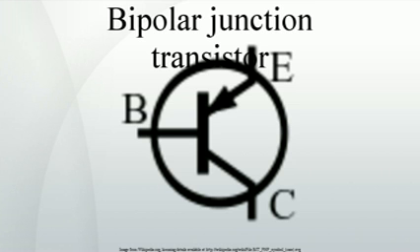PNP. The other type of BJT is the PNP, consisting of a layer of n-doped semiconductor between two layers of p-doped material. A small current leaving the base is amplified in the collector output. That is, a PNP transistor is on when its base is pulled low relative to the emitter. The arrows in the NPN and PNP transistor symbols are on the emitter legs and point in the direction of the conventional current flow when the device is in forward active mode. A mnemonic device for the PNP transistor symbol is "pointing in, proudly", based on the arrows in the symbol and the letters in the name.